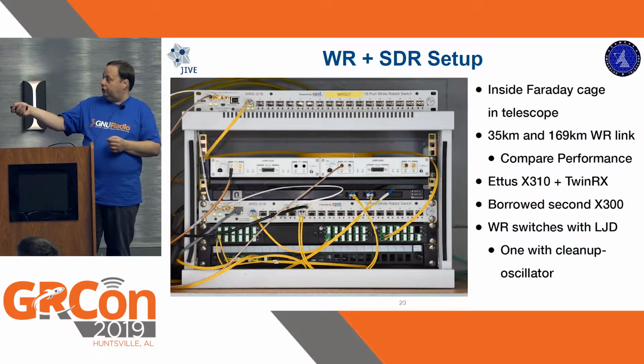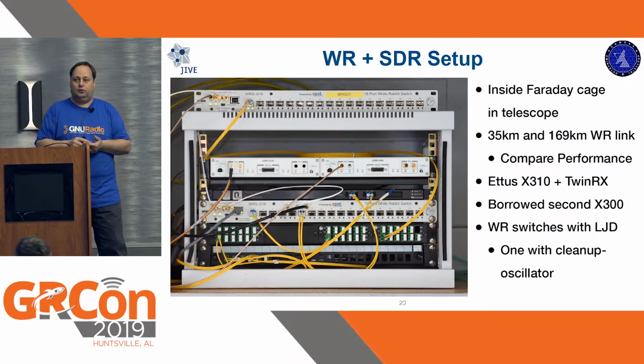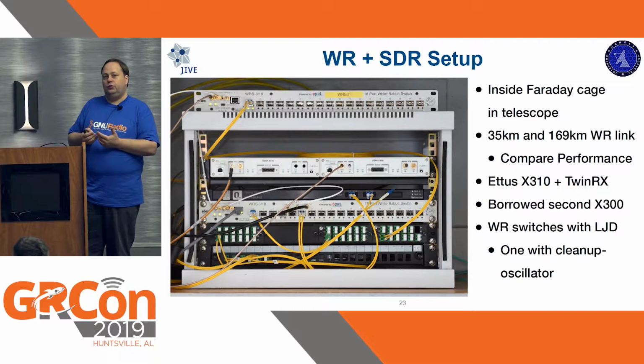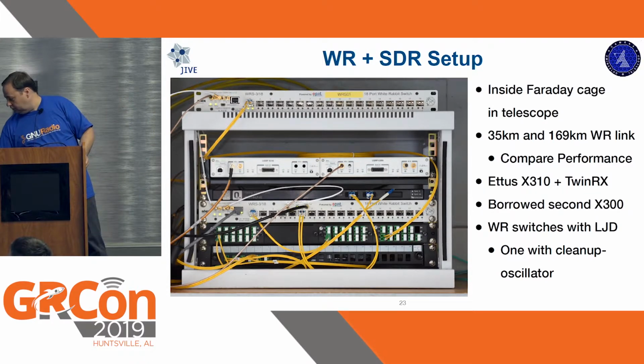I should also mention that these are not the standard White Rabbit switches. You don't get this kind of performance on the standard White Rabbit switch. We used an extension to the White Rabbit switch, which is called the low jitter daughter board. And on one of the switches, we also had a special cleanup oscillator. That allowed us to actually get to the performance that we were achieving.